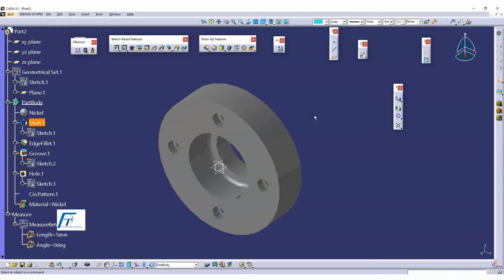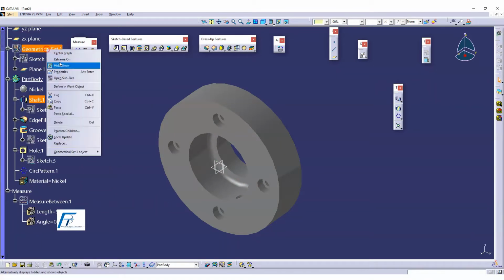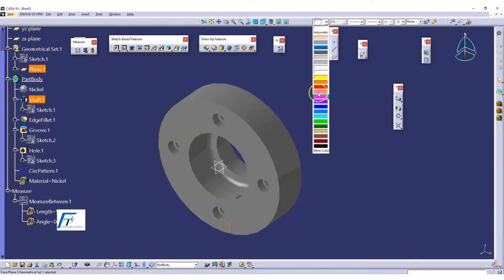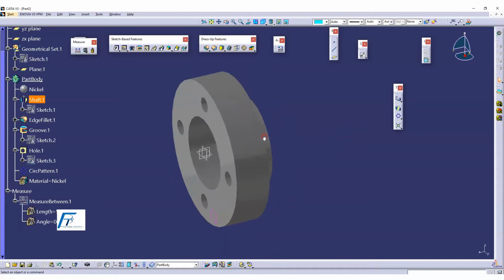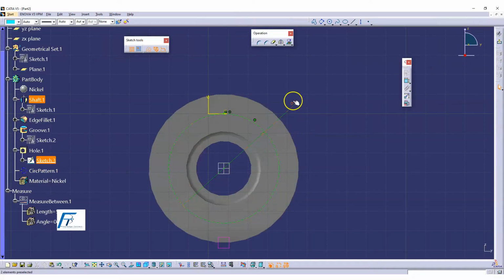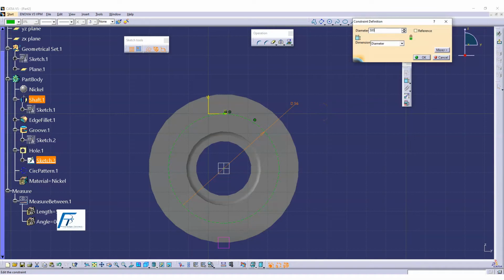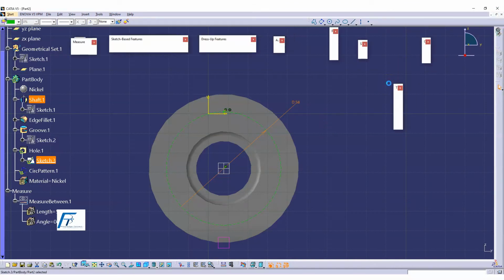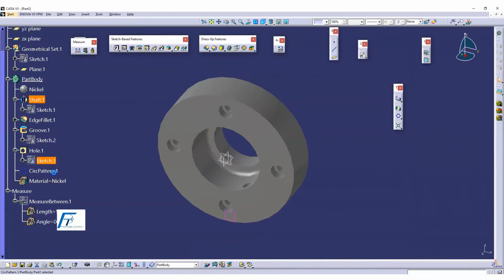So what we understand by this process, in this case, is how to use a shaft effectively, the purpose of groove, and how we use the reference element. Reference element is nothing but your point, lines and planes, right? The plane which we created, this plane, which I would like to give some color, this pink color plane. And then we understood how to give your hole position and the position in sketch, and the pitch circle diameter as a construction element also taken care of, right? So the moment you want to change this one, just change the dimension to 50 or 58, the hole position also moves. So that pitch circle diameter, we use it and followed with a circular pattern.